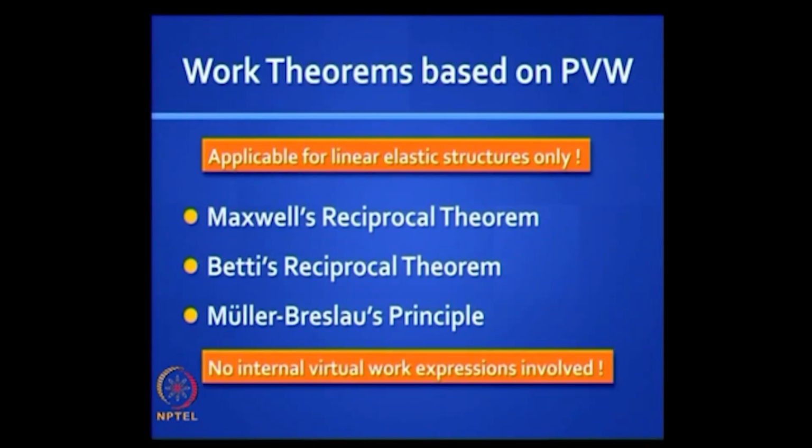And they are beautiful theorems. The important point to note is that these theorems are applicable only for linear elastic structures. And unlike the principle of virtual work, which requires you to compute both external virtual work and internal virtual work, here we skip the calculation of internal virtual work altogether.